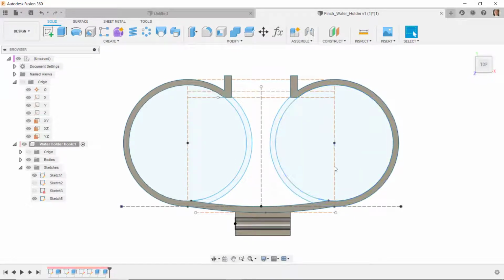But with my calipers, I can hone down on how to get those dimensions. For example, I can dimension from this point right here to this point, or from this point to this point. Now that'd be slightly difficult to measure with the calipers, but not too difficult. From here to here is pretty easy. From here to here is slightly difficult, but not too difficult. Or from here to this point is fairly easy to measure with the calipers. So I pick locations that are easy to measure with the calipers and get those into my sketch first. I would expect this arc to be tangent to this circle and tangent over here.